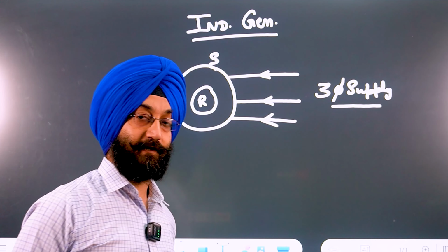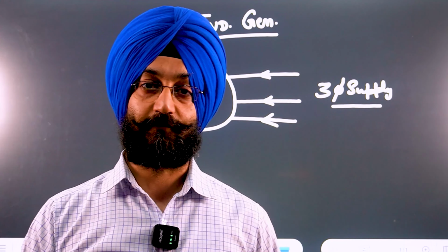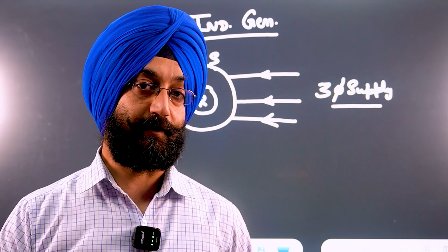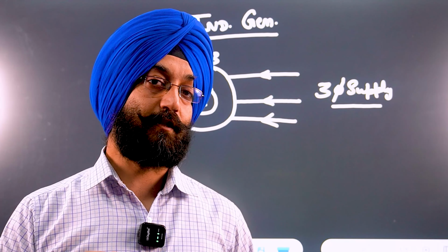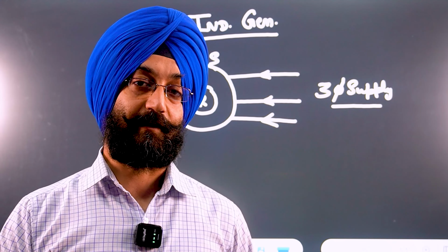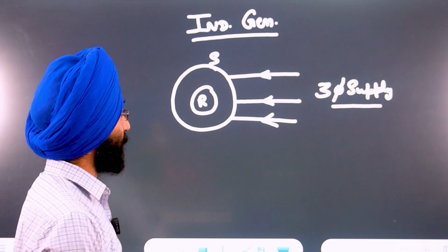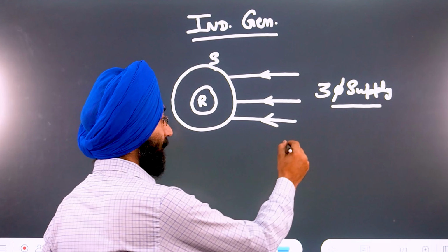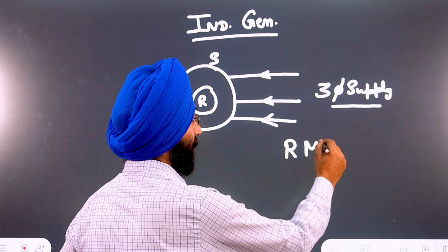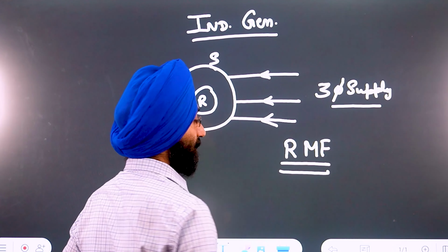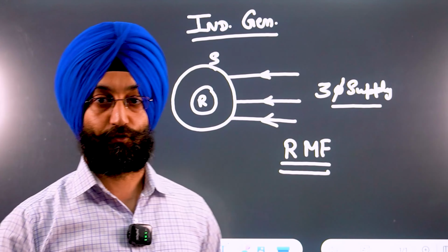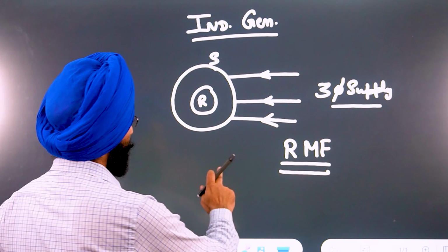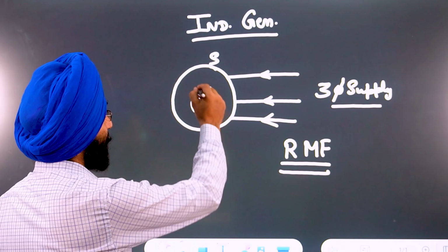whenever a three-phase supply is provided to three-phase winding of the stator of induction motor, which is spatially apart by 120 degree, the electrical signals are also 120 degree apart electrically. Now due to the winding arrangement in the stator, the three-phase winding, we will get a rotating magnetic field, which is known as RMF. This will develop a torque in the rotor itself.